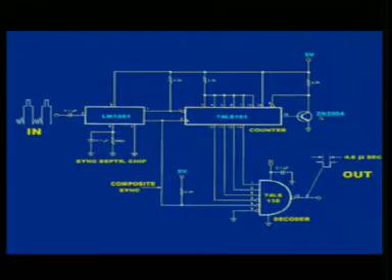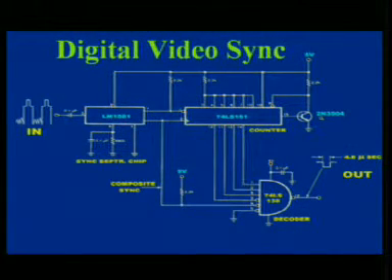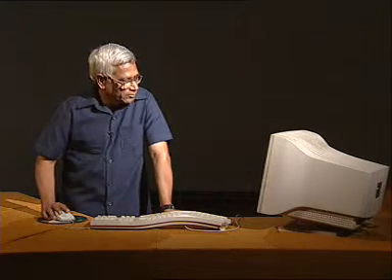So far we have been talking about the sync separation in analog form. What about in digital format? We know that we have separated the sync when the video signal is of an amplitude in which 25% level of the video signal is meant for the sync pulses. If we do not maintain the 25% level of the video signal as a sync, we may not be in a position to separate the sync. But whether the same condition is for the digital video sync, it is different.